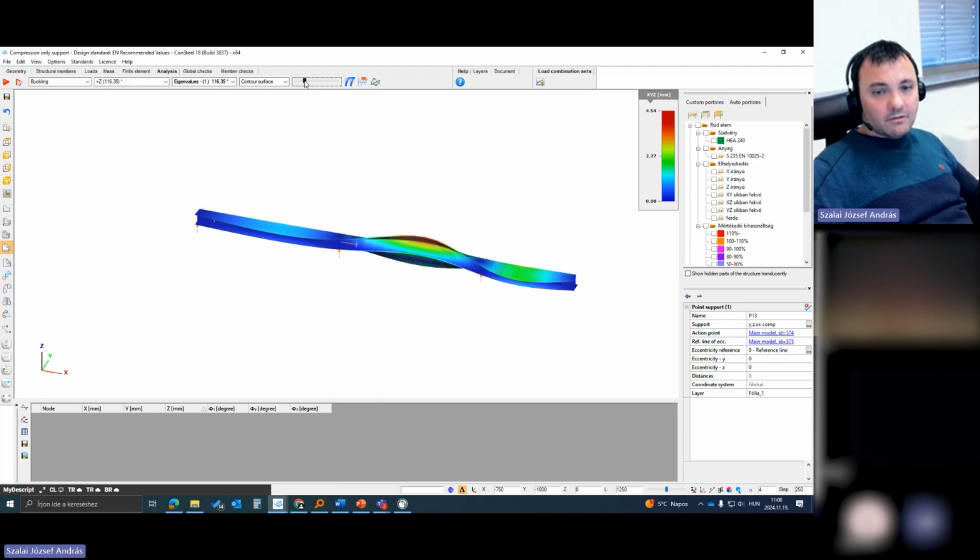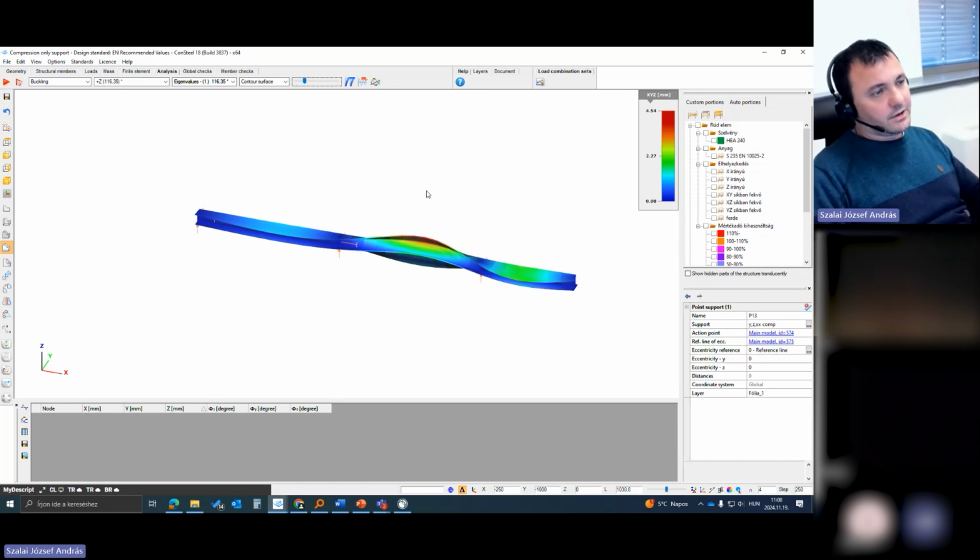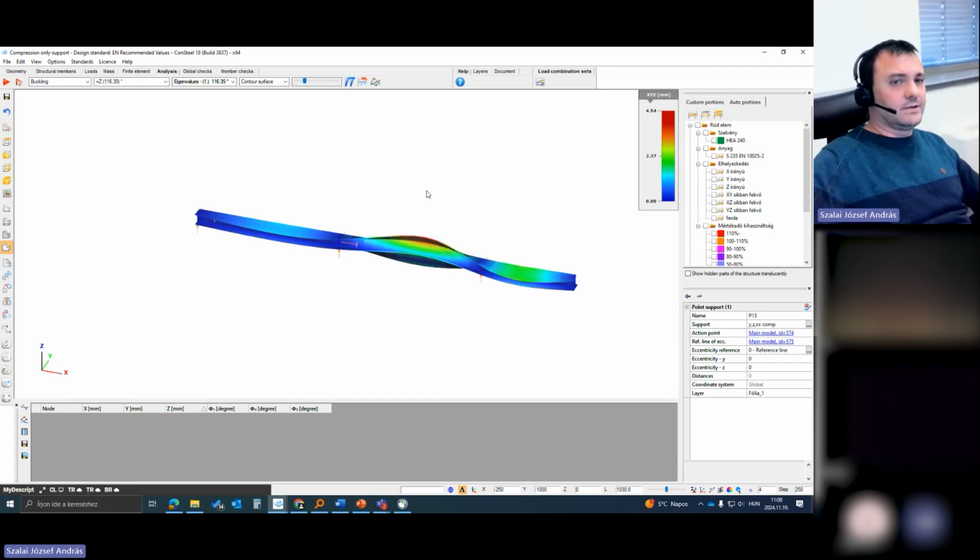So for doing the buckling calculation, we cannot apply step-by-step load increment analysis for the second order nonlinear analysis. We just have to seek a consistent state, and going further with this state, we can run all the second order, dynamic and buckling analysis.